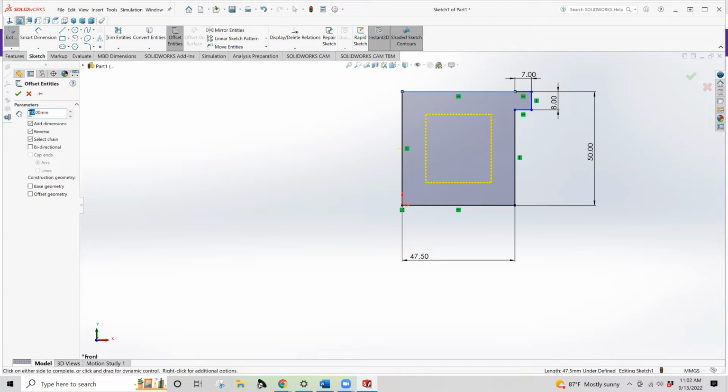We have an idea about the outer diameter, but we need to know something about the inner diameter to get an approximate value for the thickness. And this gives us right at about 90 millimeters. So those of you guessing that there should be about a 5 millimeter or so wall on most glass vessels, that would be a reasonable assumption. So here we have a 5 millimeter reference inside the sketch.